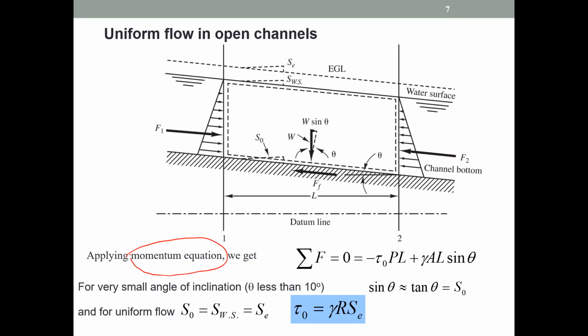In the Reynolds transport theorem, when we use momentum as the extensive property and velocity as the intensive property, we derive the momentum equation, right? So suppose that the accumulative term of the momentum inside this control volume that we consider is 0, then we can write the net force, or time rate of change in the momentum, right? Then it is equal to the net force.